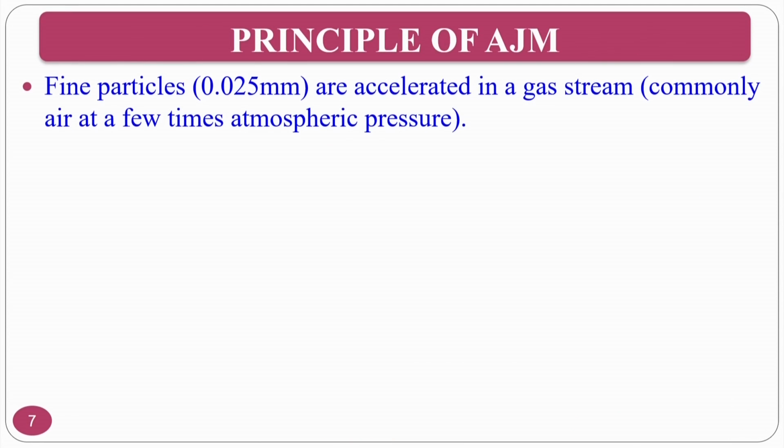The principle: fine particles, normally 0.05 mm, are accelerated in a gas stream, commonly air, at a few times atmospheric pressure. That means you can use 10 bar, 20 bar, 30 bar, 50 bar, like that. If you use bar, people will understand that. Internationally, if somebody is watching, assume that if I use 10 bar, that means 1 megapascal.